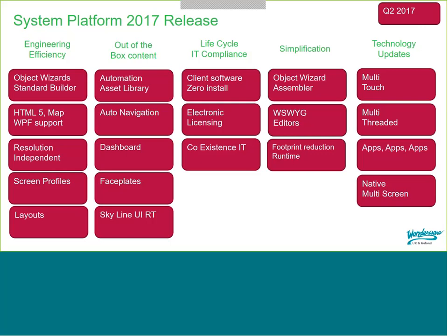So if you were using the standalone Intouch package as your visualization front end, you would have to install that Intouch on the thick clients or the operator interfaces at the other end. With this, that package actually deploys across the network. It just needs to know that that machine is part of that environment. They updated the licensing, which I'll come on to, and keeping in line with things like technology updates. They're using some of the latest technologies, and it's now multi-threaded, which talks to the whole business of reducing the amount of resources required to run your system.